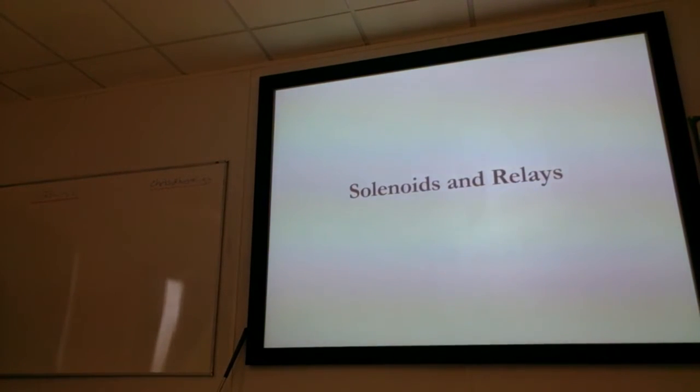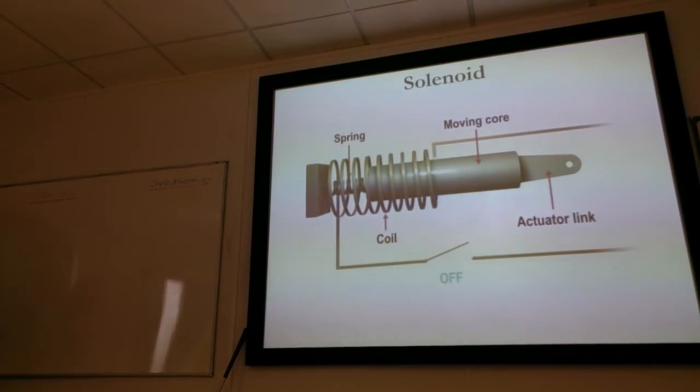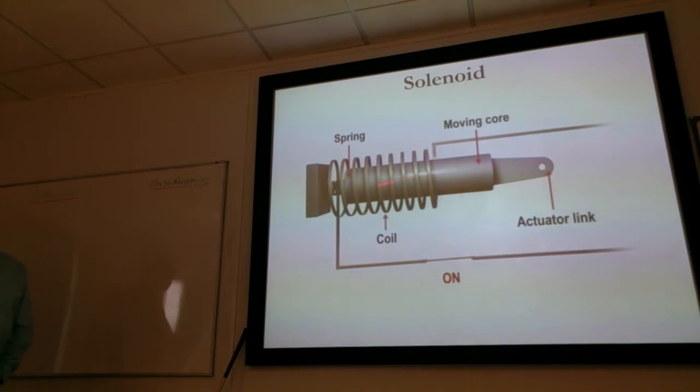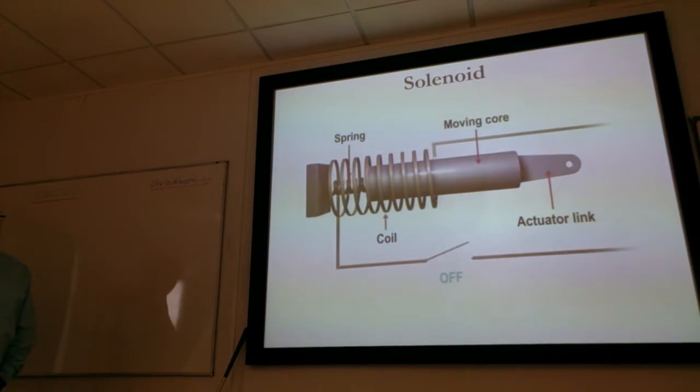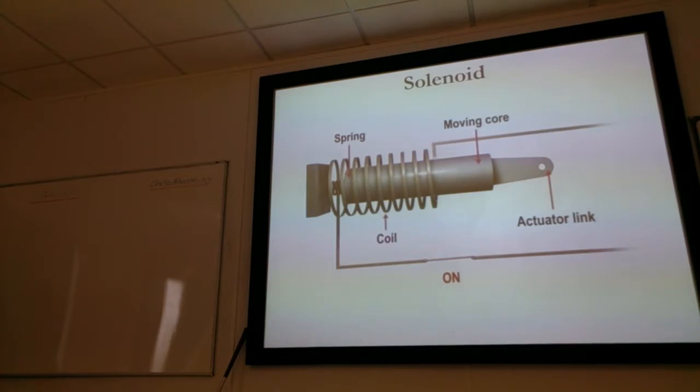Come back. Thank you. Okay, there's a coil. There's a piece of soft iron. We energise the coil and we make that a magnet. We de-energise it and it stops being a magnet. We've now got ourselves an electrical method of turning something on and off. So we can control valves with it, we can control switches with it. A solenoid, just an electromagnet, simple as that.